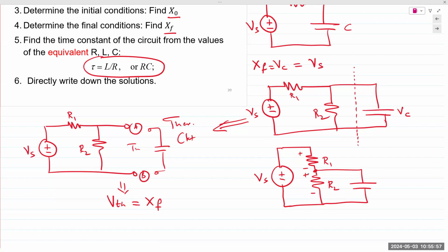That change in capacitance is detected and registered as a touch, converted into an electrical signal. Previously, it used to be resistive touchscreens. With resistive touchscreens, you had to apply pressure. When you applied pressure, it would change the resistance value, and depending on the spot where the resistance changes, that is transferred into an electrical signal.